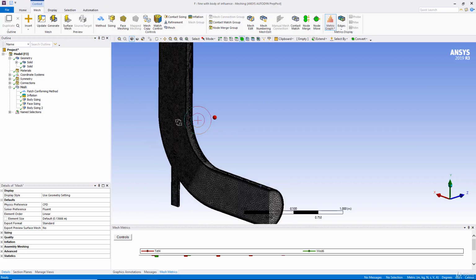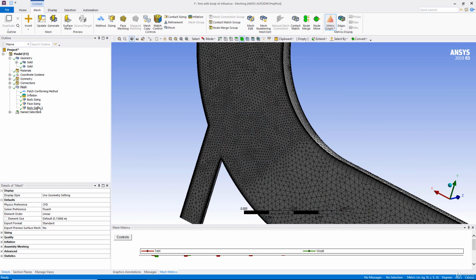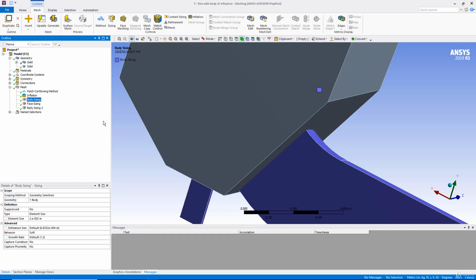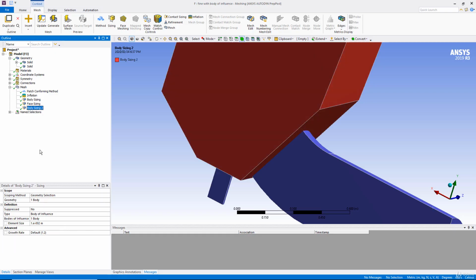And now you can see that we have the refined mesh, which has a cell size of 0.01, and in the overall body of this elbow, the size is up to 0.02. This is the maximum size which we can get here, and depending on the local condition, size might reduce to some lower value also. So here we limited the maximum size of the mesh in the whole domain volume. So the size cannot go bigger than this value. So in this way we define the mesh.